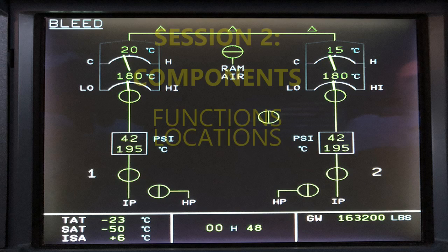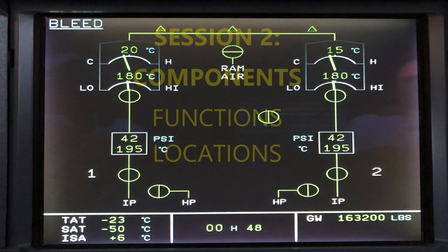Okay, and of course, if the temperature downstream goes below the required value, then certain things are going to happen. You've got the valve that's going to remain closed, no air flows through the pressure regulator, and you've got the invar rod valve that's just going to remain in its position.